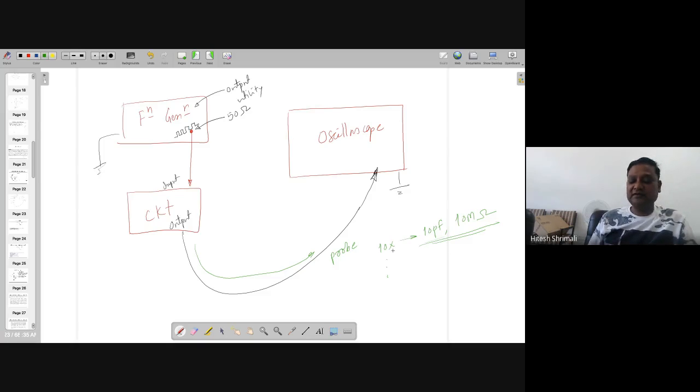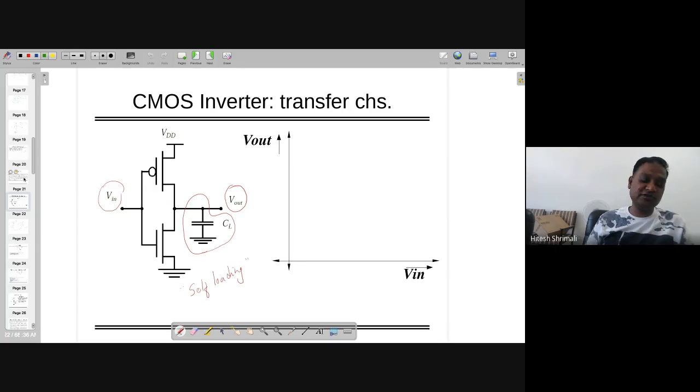If you look at the available probes in our laboratory, IIT Mandi's laboratory, you will see it's 15 picofarad with something like 15 mega ohm, or some number near these numbers. And if you go for 100x, it becomes 150 pico, 150 mega, and so on. So generally, we consider that as a load. If you are going to see this on an oscilloscope, you have to connect the value accordingly. If you are going at 1x, generally we take 1 picofarad because that's coming from there.